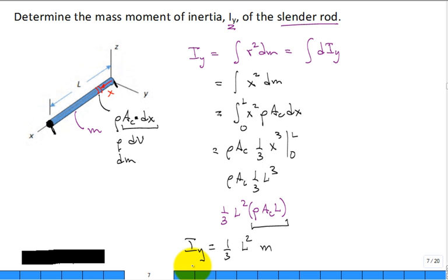So I sub y is 1/3 m L squared. Can you see what I sub z would be? Same thing, isn't it? 1/3 m L squared. How about if somebody says, not this y-axis, put it through this y-axis, going through not the beginning of the rod, but the end of the rod. Guess what? 1/3 L squared M. So there you go, 1/3 mL squared.